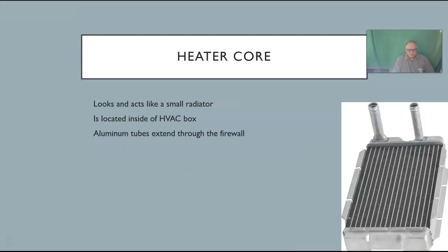Heater core looks like just a small radiator. So those two tubes that you see up at the top, those are going to be sticking through the firewall, and that's where your heater hoses are going to connect up to. The water pump is going to circulate the coolant through the heater core, so as the engine warms up, it's going to warm up the heater core, and that's what's going to provide the heat inside of the vehicle.